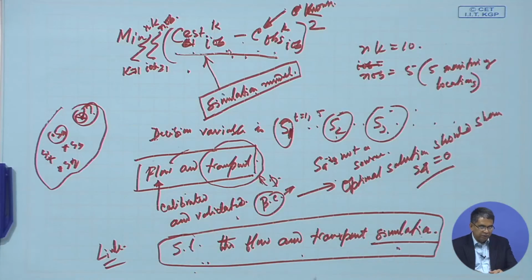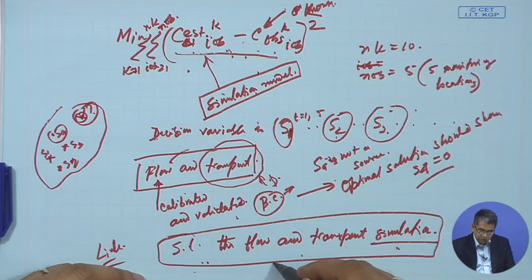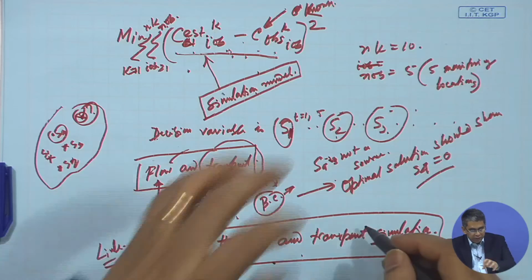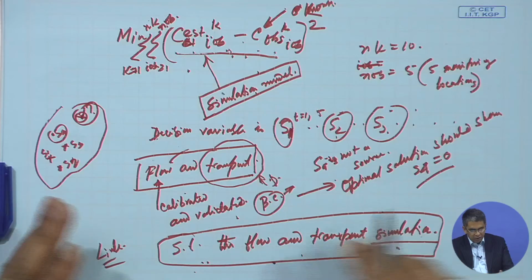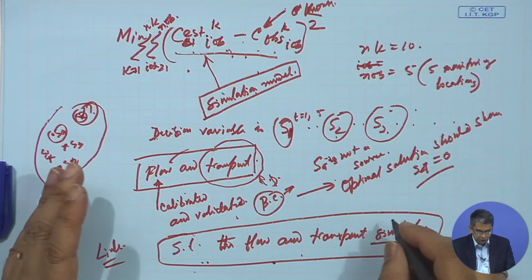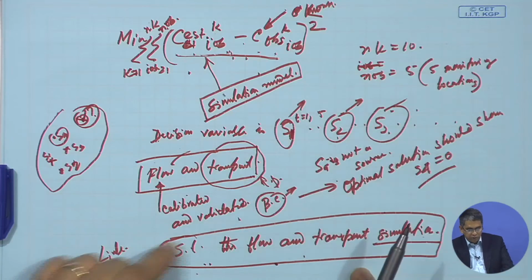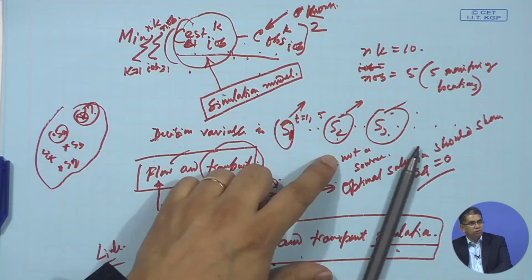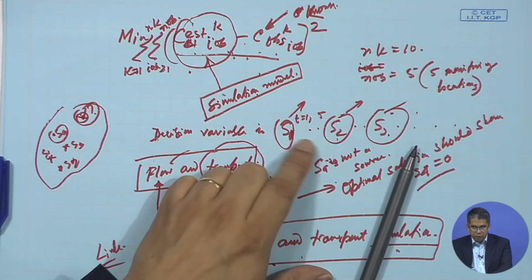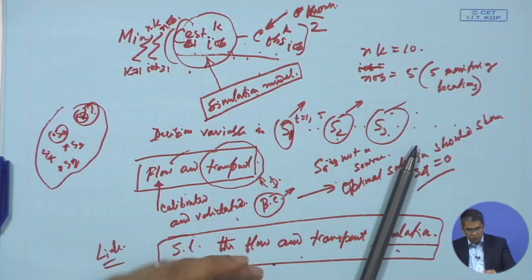So, these are generating those candidate solutions, going back to the simulation model, and then find out if these are the sources. And because I know everything else, I know the flow model that is calibrated, I know more or less the boundary condition, but I do not know exactly the sources, but I input these as sources in the input file, and then find out from the simulation model what is this estimated C for these source values. Okay. So, for this candidate solution, which is generated as a possible solution by the optimization model, I put that as input to the simulation model.